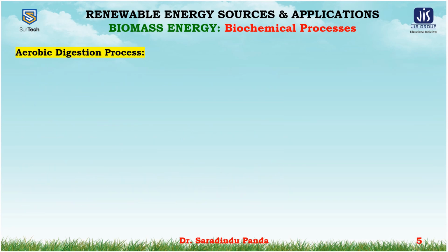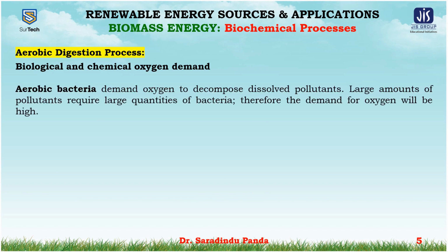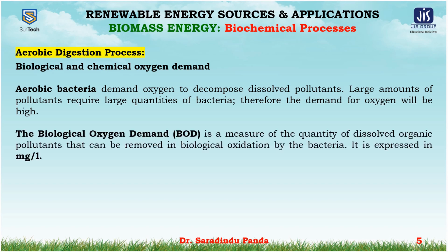In the aerobic digestion process, there is the biological and chemical oxygen demand. The aerobic bacteria demand oxygen to decompose and dissolve the pollutants. Large amounts of pollutants require large quantities of bacteria. Therefore, the demand for oxygen will be high. The biological oxygen demand or BOD is a measure of the quantity of dissolved organic pollutants that can be removed in biological oxidation by the bacteria. It is expressed in milligrams per liter.